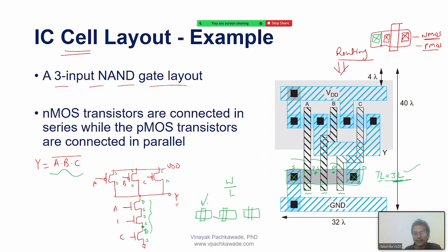Once you select a particular transistor from the library and double click this instance, the parameter window will open up and it will allow you to set W and L. So if I set L equal to, for the 10 nanometer physical size, I set L equal to 30 nanometer and W for whatever W, so the transistor will look longer. Okay, this is the transistor that I will have in the window to be placed.